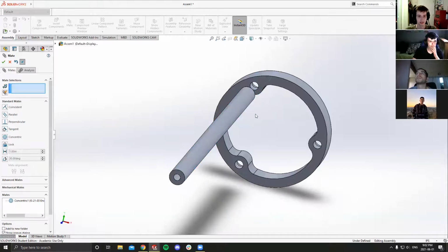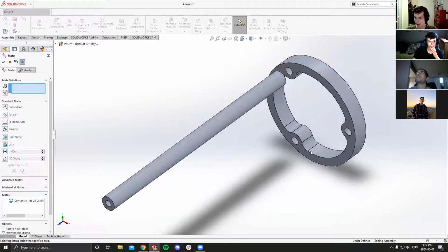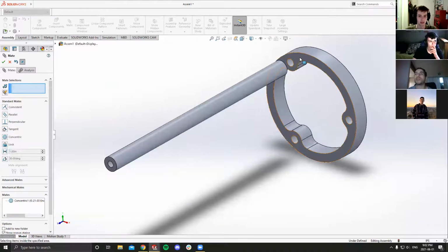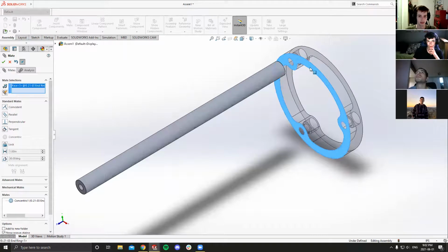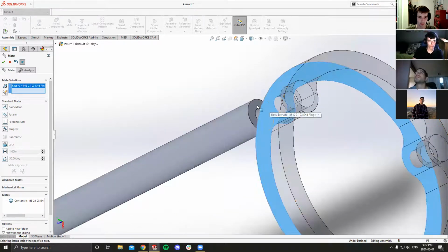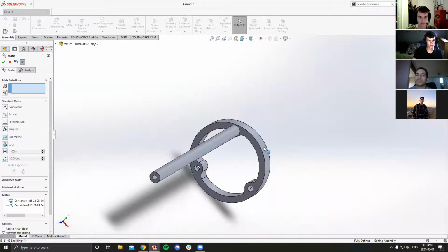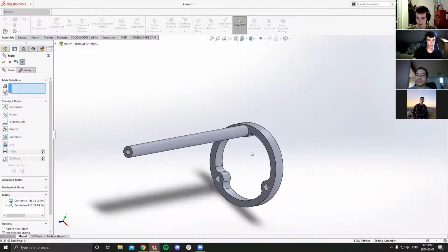And so now we only need to define its position in one more spot, and that is along this axis. And so how we're going to do that is moving on to slide 36, step A6. We're going to mate the two faces. And so I'm going to select this flat face, and I can use the middle mouse button to rotate around and click that face. And you can see it brings us a nice coincident mate. We'll confirm that. How is that for everyone?